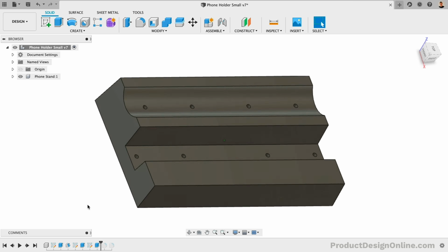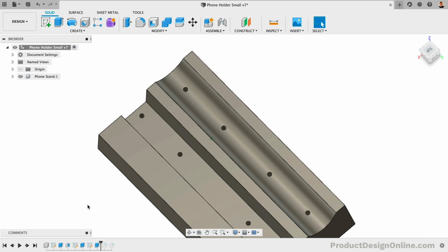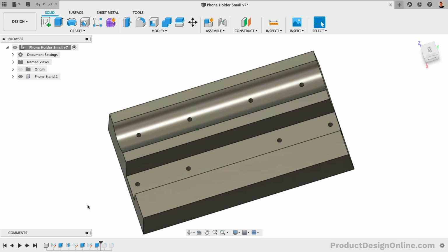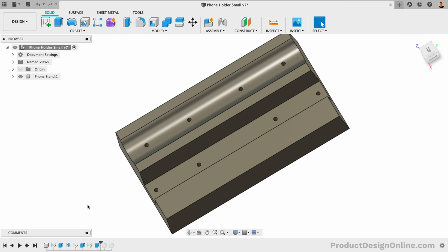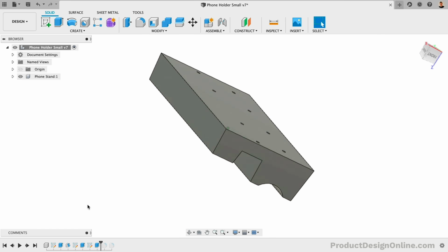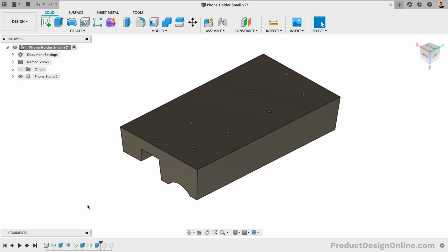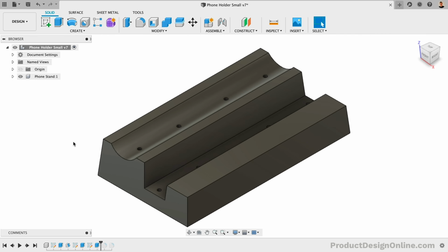The key consideration with these holes is that they need to be small enough that they don't affect the mold. This is one of the first problems I ran into with my initial prints in vacuum forms. Through some trial and error, I found that 2 mm was the optimal size that allowed the air to pass through without leaving noticeable divots in the final mold.